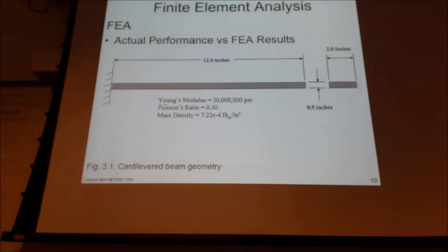And if you consider materials like injection plastic molding, 3D printing, or casting, where the material isn't as homogeneous and isotropic as steel, then there's more sources for error and changes in parts. Geometry would be another source of error. For this specified size of steel, it might vary by as much as a 32nd of an inch. Which doesn't sound like a lot, but it can certainly make a difference.